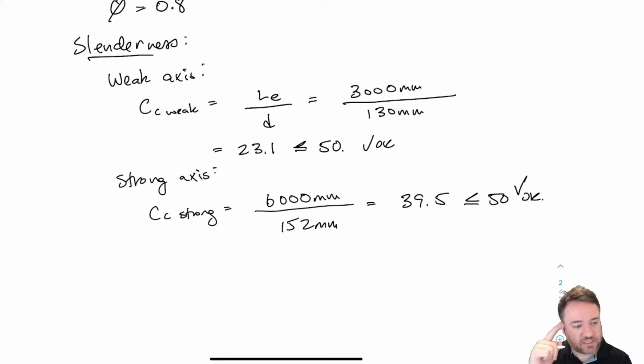Why? Because the KZ factor also changes based on which dimension I'm talking about, based on which buckling direction, and the effect of that is reversed. So it's not clear before you actually do the calculation which one is going to govern. Although in most cases it's still going to be the slenderness that governs, it's just not guaranteed to be the case. So I have to check both for lumber. But since this is Glulam, let's continue and check the slenderness factor.